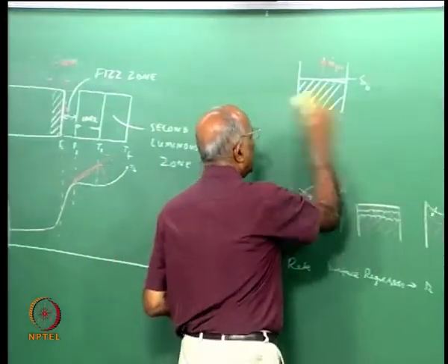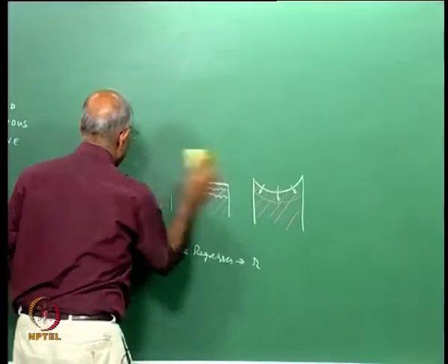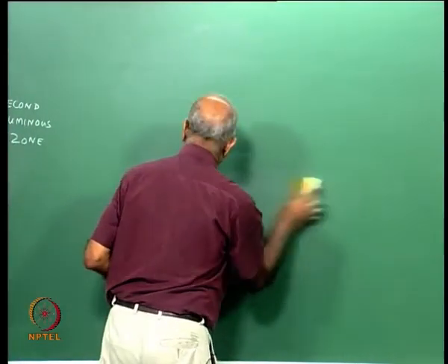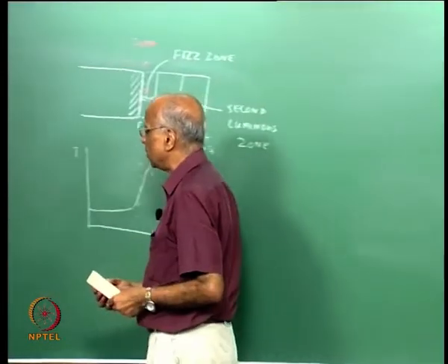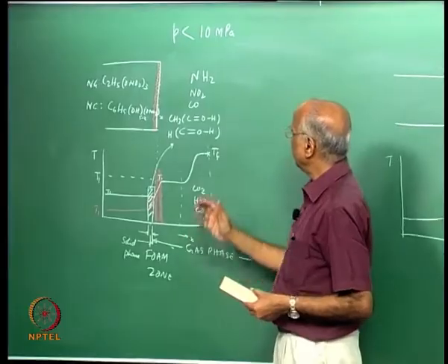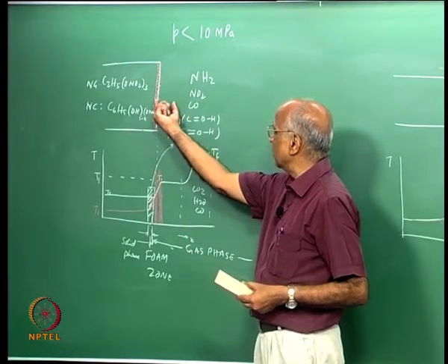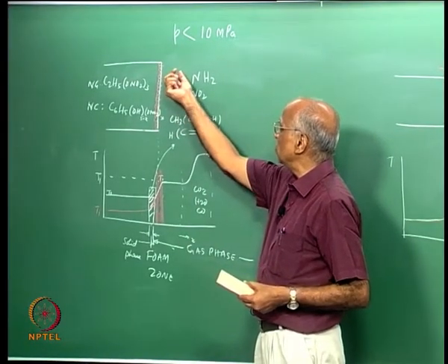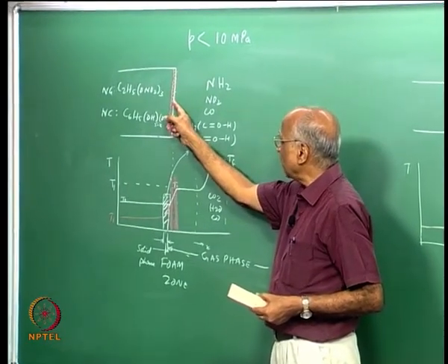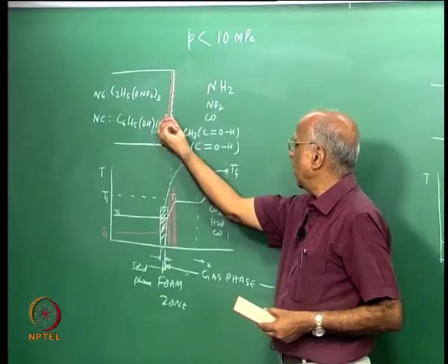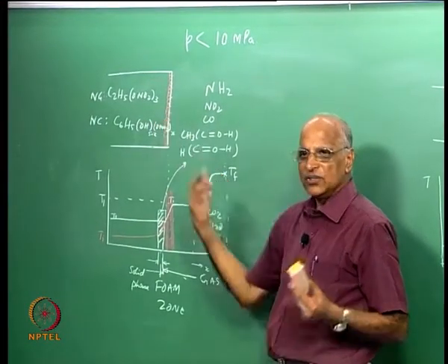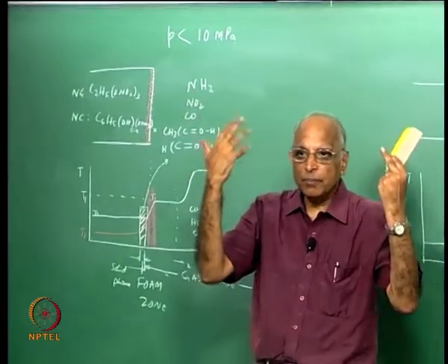In other words, what is the model, or what is my mental picture, that I will have in mind? For us to do any problem, it is necessary to first consider the physical problem. Like we looked at the sparkler, we say yes, regression takes place. We tell ourselves, heat is generated here, the temperature in the fizz zone is T1, heat gets conducted from T1 to the surface, and if I can calculate this heat which is conducted, then I can write the equation at the surface and get the burn rate.